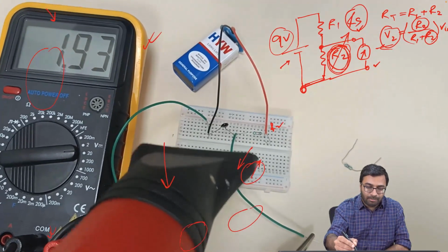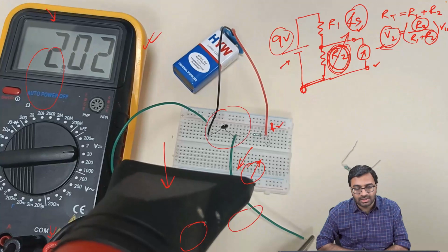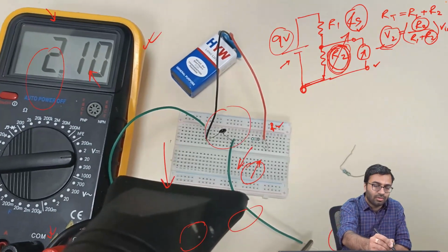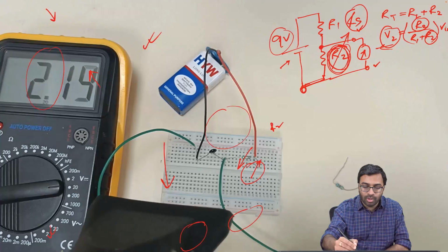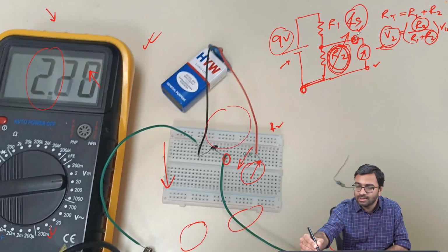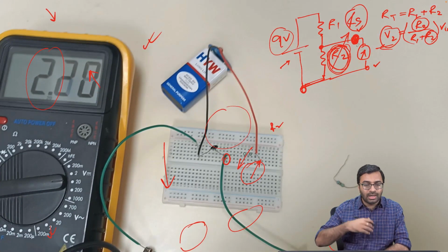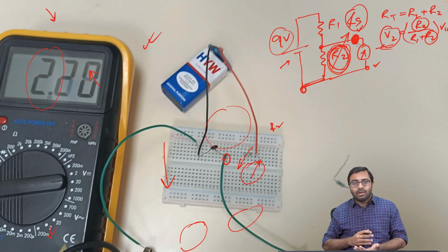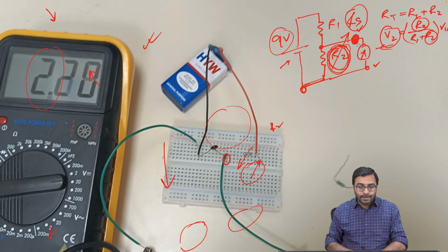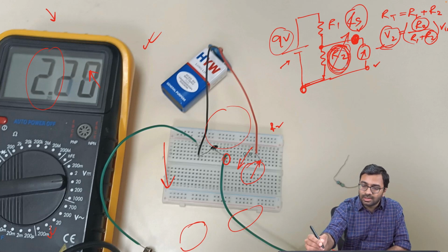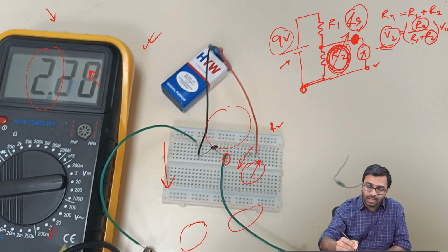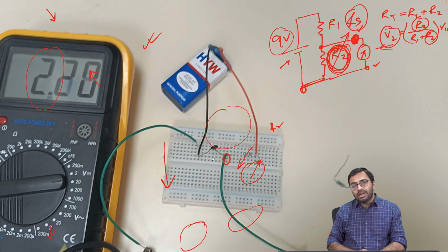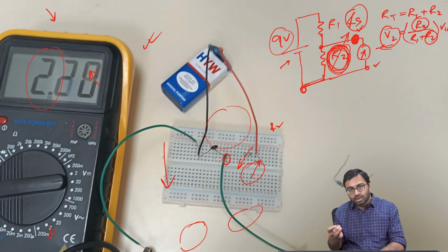Now because the temperature around this sensor is changing, you will find the same change over here in terms of voltage. Now you can take this, that is this analog output, to the next level of the system. So you can use that output for your sensor system design. So in this experiment, you can see that if you replace this resistor with a sensor, then you can also integrate the sensor in a voltage divider circuit, and you can take the analog output to the next level of the system.